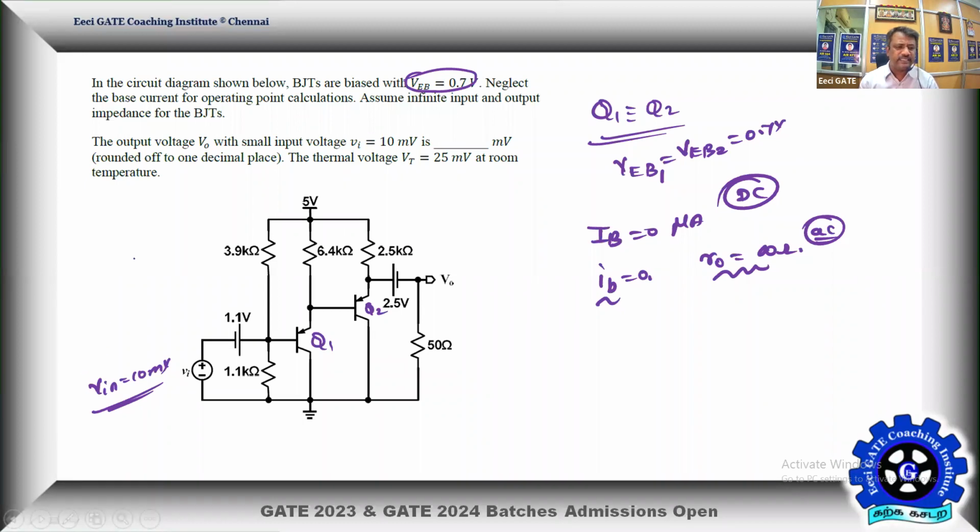It's a DC, okay. So a DC voltage is applied around your Q point. So then what will be the output voltage V0 with the small input voltage? There is no capacitor in this. Usually in transistor amplifier circuits, we go with AC, but intentionally he's playing with the DC now. So it's a small incremental change. You take it as an incremental change in the Q point at the base and how it is going to make a change in the emitter of your second transistor, that is given as V0. That's the expected output. Simply let me take this as an input voltage Vin like an AC and this is the output voltage like an AC. So that's the AC small signal analysis we're going to perform.